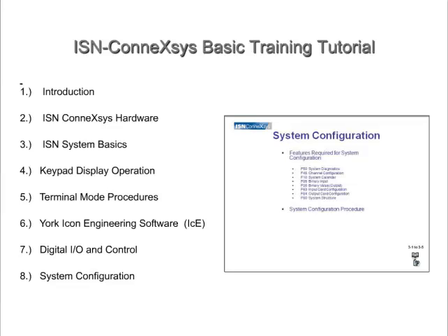In this next section, we cover system configuration and setup. Field wiring checks and power-up procedures are covered. Feature 50, System Diagnostics, is explained. Feature 45, Channel Configuration, is where we set up the communication parameters for the COM ports, like baud rate, start bits, stop bits, and parity. And next we move on to coordinated lab exercises.